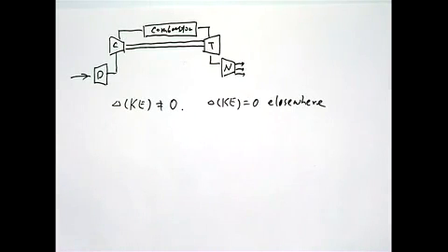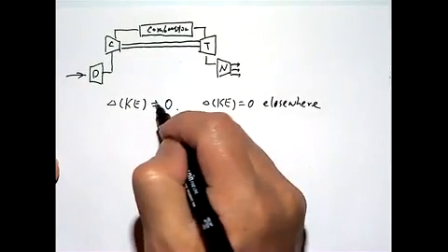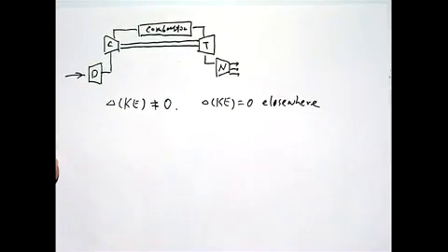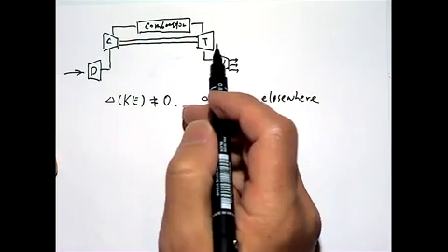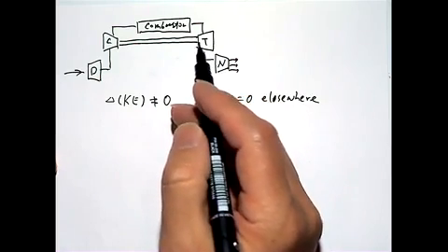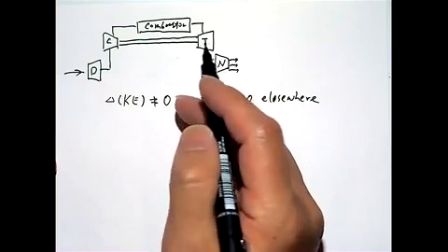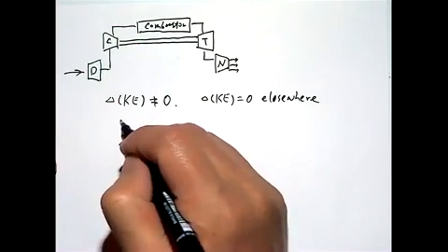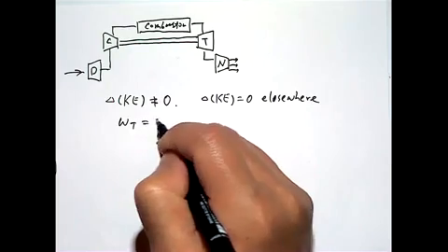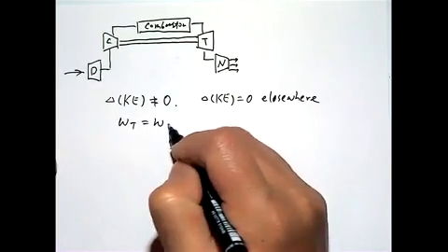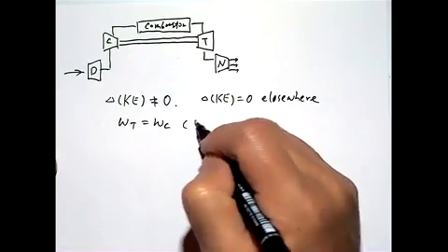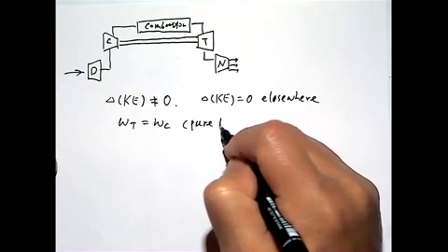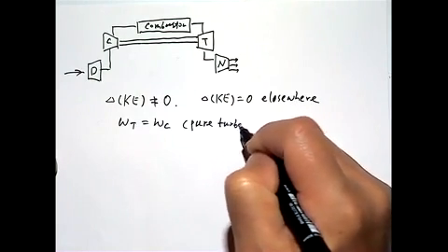Another thing is, in this pure turbojet cycle, we consider that the turbine does not output useful work. As said, the function of the turbine is just to drive the compressor. So the work at the turbine equals the work of the compressor. So that's for this pure turbojet cycle.